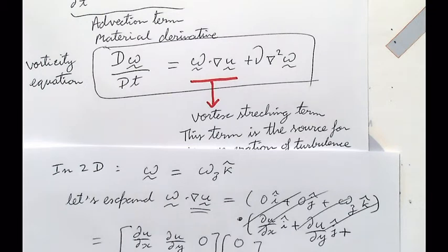Is it necessary that if the stretching term is 0, there will be no turbulence? We have the advection term and there can be instabilities at very high velocities which can generate vorticity, but there won't be any cascading if the stretching term is 0. So we can have turbulence in 2D, right? You mentioned a lot of things that we have not talked about, and will probably not talk about. For the last 2 classes, I will cover more of what happens in turbulent flow, how we simulate and model it.